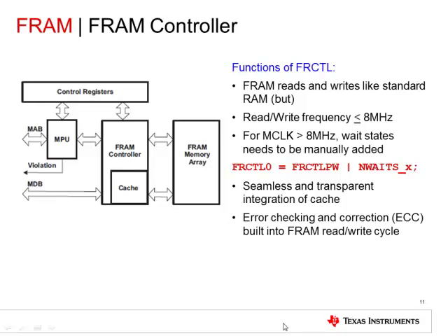When the system frequency is set to higher than 8 MHz, wait states to access FRAM need to be configured in the application using the FRAM control register. The FRAM module also has built-in ECC logic that is capable of detecting and correcting bit errors.